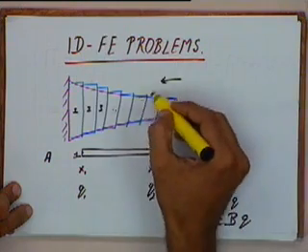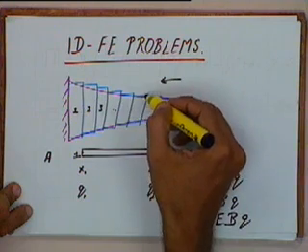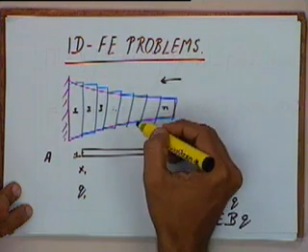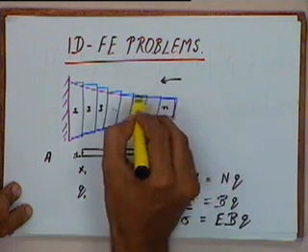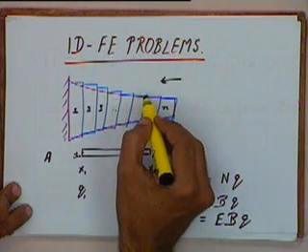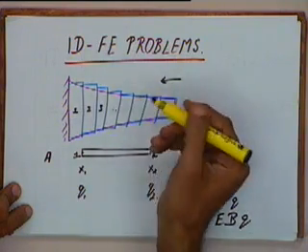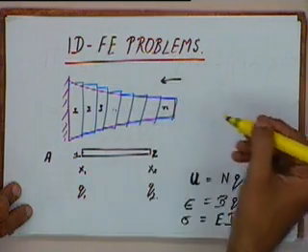So if I am talking of one dimensional forces over this element acting on the surface, that force has to be along this length. So then really we are only talking of some shear kind of forces. So instead of that force being on a per unit area basis, I can treat that as a force on a per unit length basis.